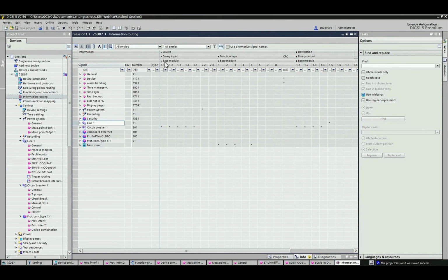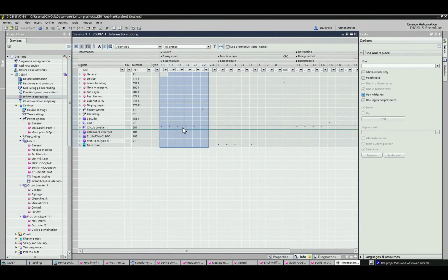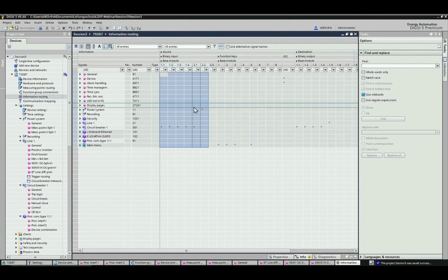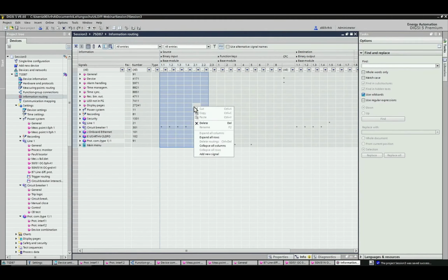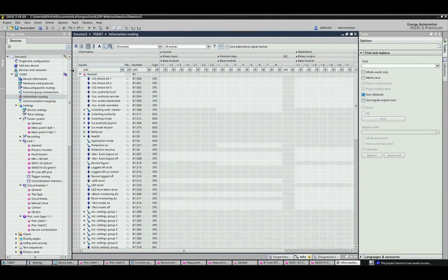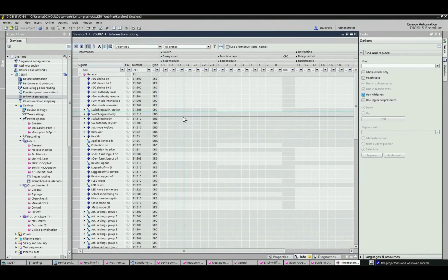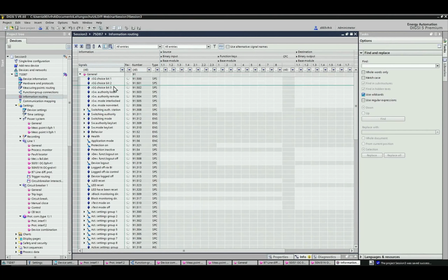So the next thing is I want to do some routings for the binary inputs. At the moment we do see some default assignments for the circuit breaker, the circuit breaker position and so on, but they are not interesting for me in this example, so I delete them to have more free space. What I want to add are connections for switching the test mode on and off, or switching the different test modes on and off, because I want to explain to you what test mode options we have in the SIPROTEC 5 line differential protection.